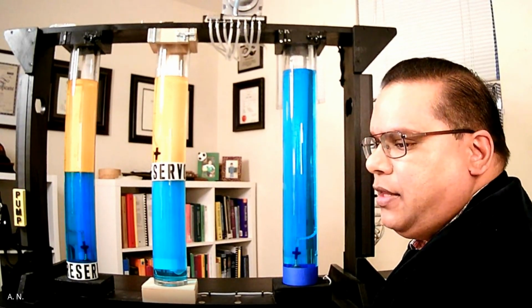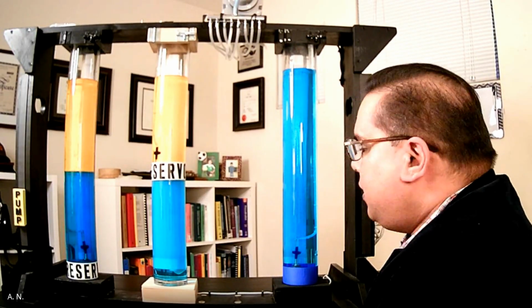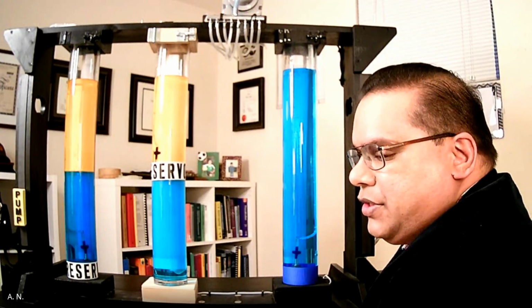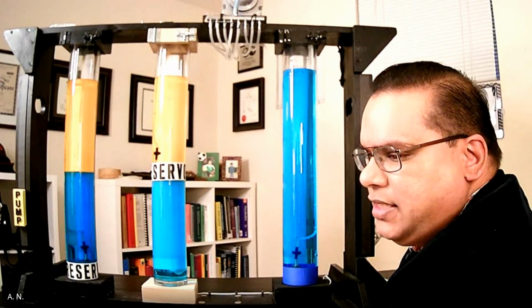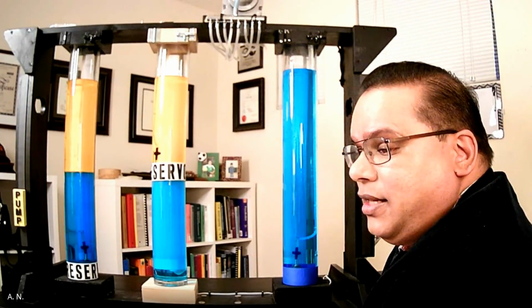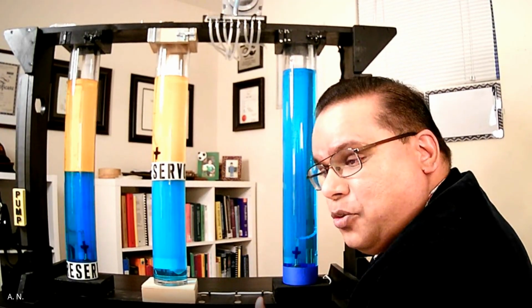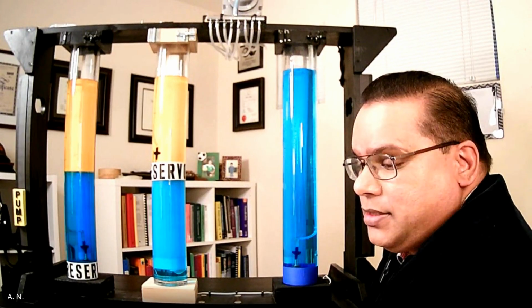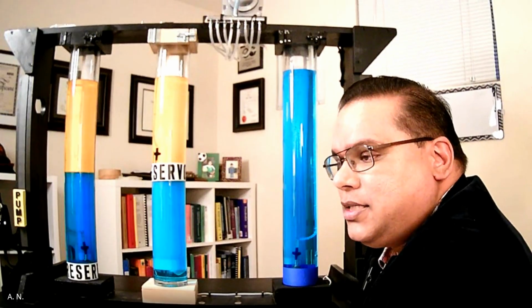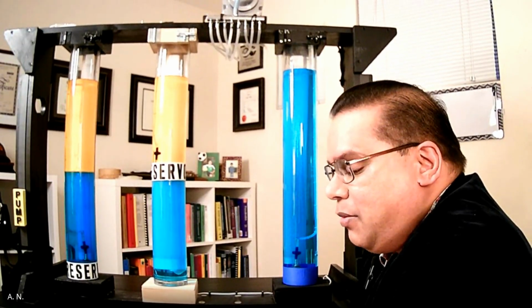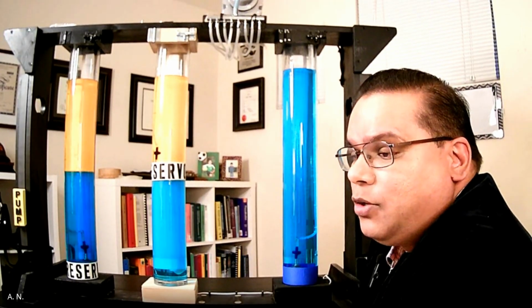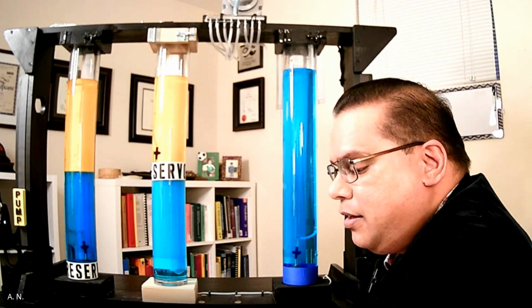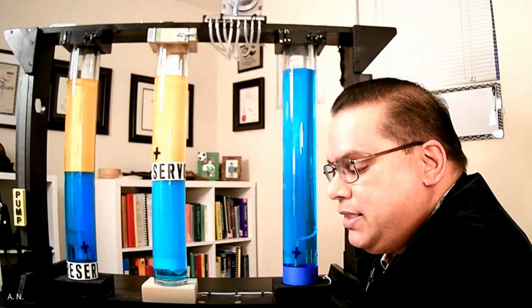That is what we've seen in different types of course, it changes according to the type of fluids and so on. But basically, the general observation is that, right? Now that immediately contradicts our 6-inch per second rule, because if you really understand where that 6-inch per second rule for a 1/4 inch bubble diameter came from, it's a completely arbitrary thing. It was just generated for a liquid flow rate of 50 barrels per day in a 1-inch annulus, right? Believing that the gas rise velocity would need to be 6 inches per second.